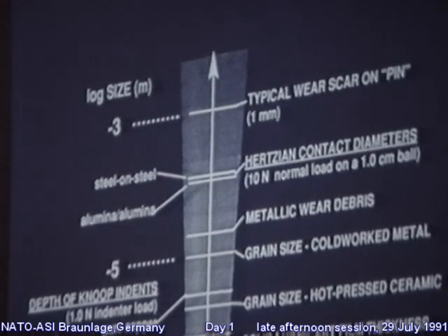And before I leave this, it's interesting that some of the nominal pin-on-disc type wear testing machines produce areas up in the minus 3 to minus 4 range, perhaps a little larger. And then we have some devices which are rather finely tuned, very small contact area, low load, in which we might approach some of the tens of microns. And I'll be talking about the friction microprobe shortly. We're going to be talking about between about 2 and 15 micron contact size. Down here we have the atom probe type instruments. And in such, I'm looking forward to hearing about those next week.